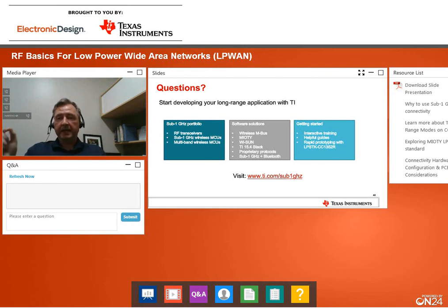So that is one option. But the other option is that your signal occupies more than 500 kilohertz of bandwidth, effectively looking like a Wi-Fi signal, because the original FCC spec is written quite well to basically be Wi-Fi compliant and BLE compliant. So we can choose which one to be compliant with.